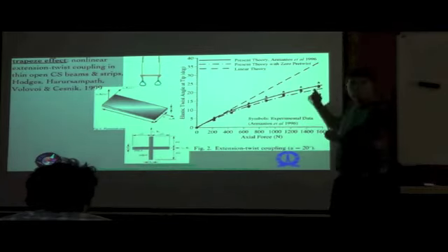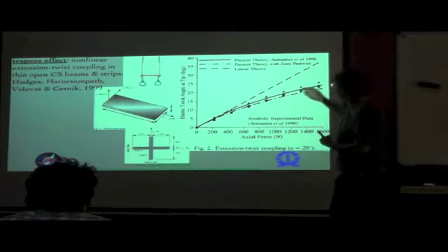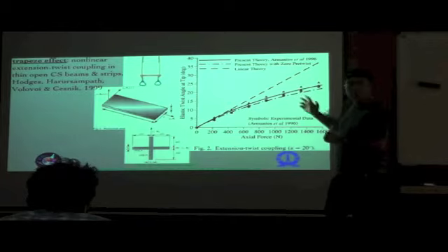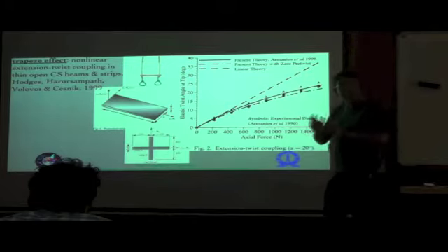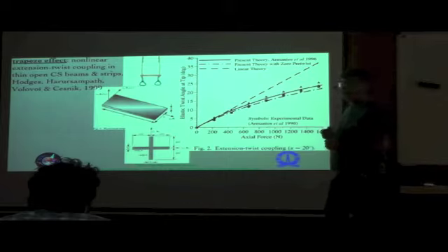This was a fairly small value of pre-twist, and even for that you see there is quite a difference, because the pre-twist plays quite an important role in the trapeze effect. In particular, it not only changes the nonlinear behavior, but the linear part of the nonlinear behavior is also changed by the presence or absence of pre-twist. So that's the reason why that is important as well.